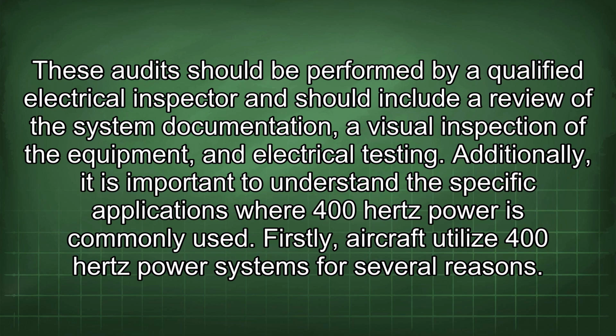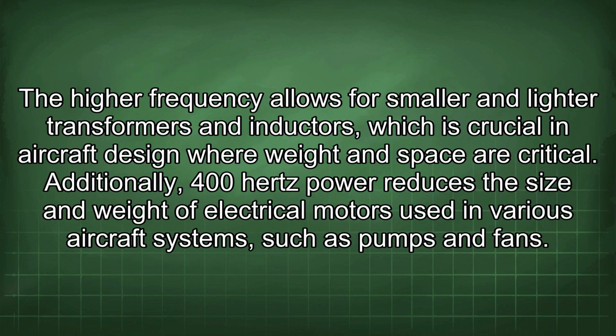Additionally, it is important to understand the specific applications where 400 Hz power is commonly used. Firstly, aircraft utilize 400 Hz power systems for several reasons. The higher frequency allows for smaller and lighter transformers and inductors, which is crucial in aircraft design where weight and space are critical. Additionally, 400 Hz power reduces the size and weight of electrical motors used in various aircraft systems, such as pumps and fans.